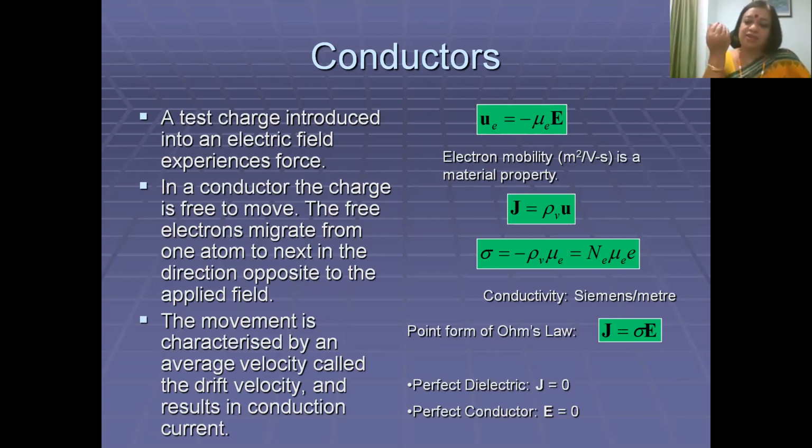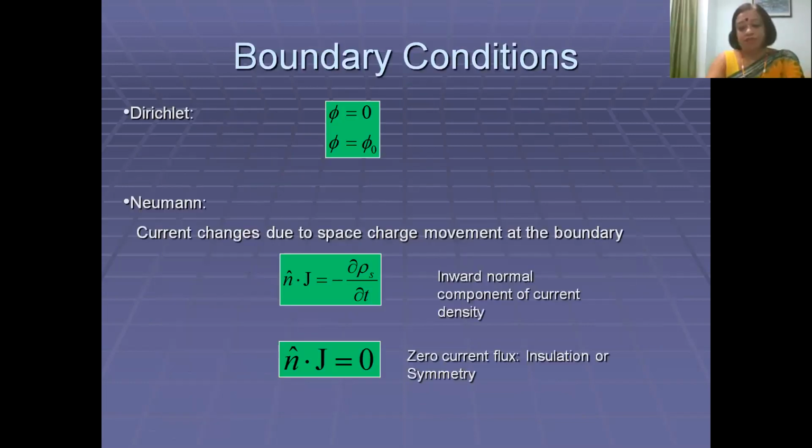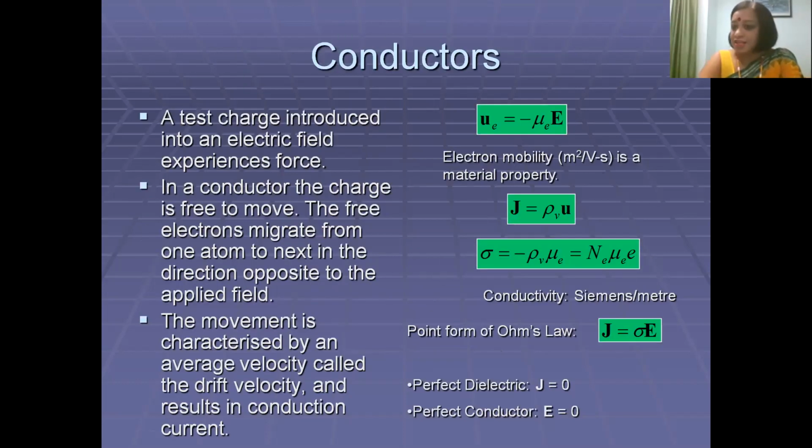I again stress that when we are talking about circuit models, we don't bother with the electric field distribution, because in circuits, we are taking a particular conductor shape and configuration, and we assume that the current density is constant throughout the area of the conductor. We can consider thin wires, and we consider only potential difference, so E is equal to V by d. But that need not be true for a conductor which is not necessarily a thin wire conductor.